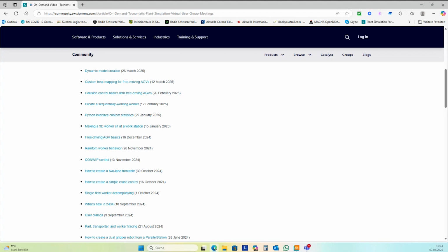So with SQLite, can I connect to an internal data table? No, you cannot. SQLite is a database, and you can connect internally to this SQLite database. The data table is an object in Plant Simulation, and this object doesn't support SQL queries. So SQLite is a complete database. It's integrated in Plant Simulation as a module.